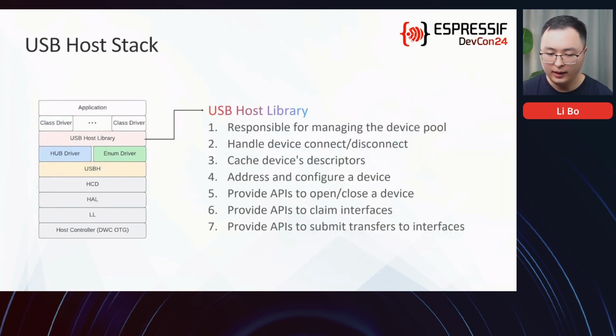And if the class driver you want to use is not currently supported by ESP-IDF, especially for some vendor-specified devices, you may need to develop your own class drivers based on the USB host driver, which may not be as difficult as you think, because the USB host driver internally handles the USB connection and disconnection, and also enumerates the devices, sets the device address and caches device descriptors in RAM. You can fetch your descriptors at any time.